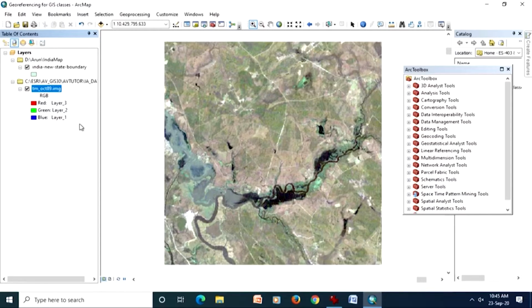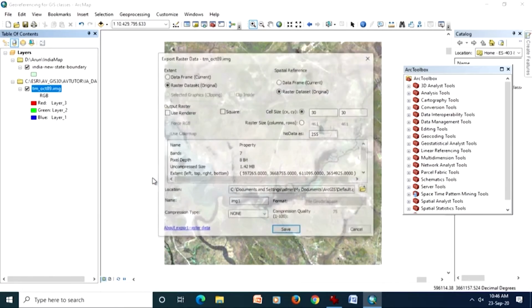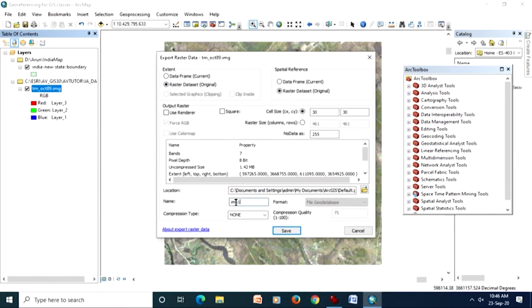So, in ArcGIS software, when we want to save some file, suppose here I am having this one file which is in IMG format, a satellite image, and if I want to save it, at places I will get these options of data compression. Like if I go here and save my data, export data, that means I am going to save in a different format, which I can choose here. If I don't choose, then I am having the option for compression type.